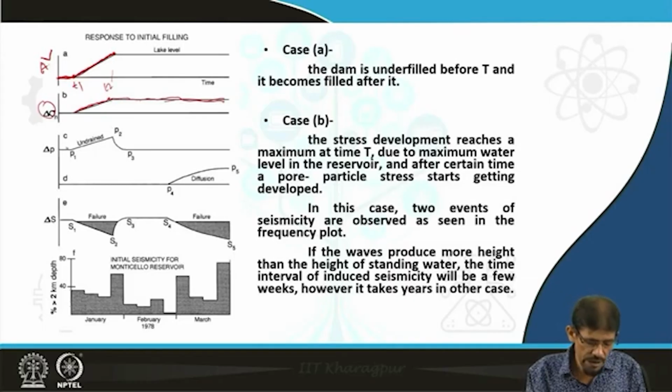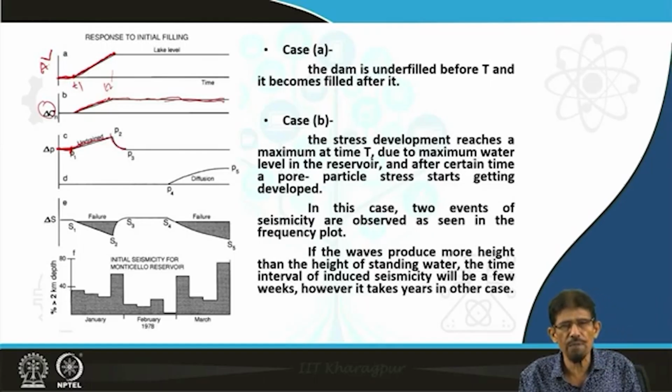Beside this, here you can see, initially there was no development of pore pressure. When there is an increment, there is a development of undrained condition and an increment in pore pressure, which is going to reduce the effective load of the water-induced normal stress, and then it stabilizes.